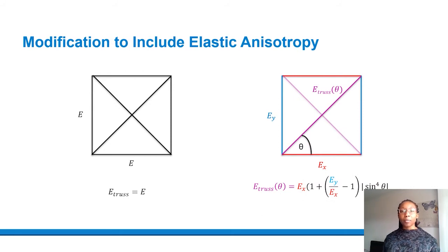In this particular work, peridynamics was implemented in Abaqus. In this implementation, the Abaqus trusses represent the peridynamic bonds, whereas the Abaqus nodes represent the material points. In the isotropic case, the elastic modulus of the elastic trusses was constant, but in the anisotropic case, the elastic modulus was set to have an angular dependency.